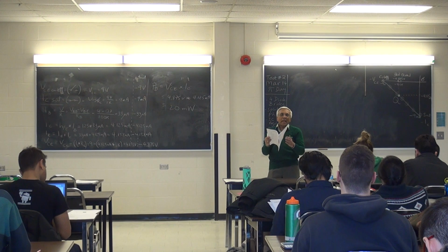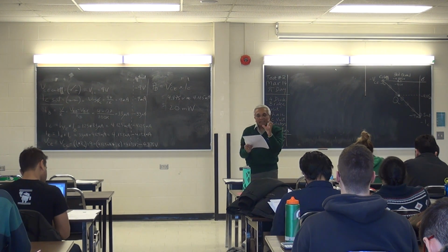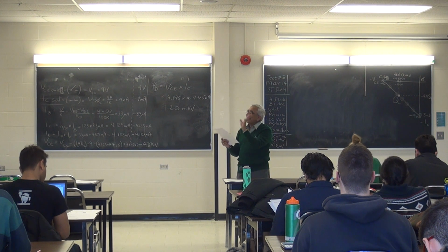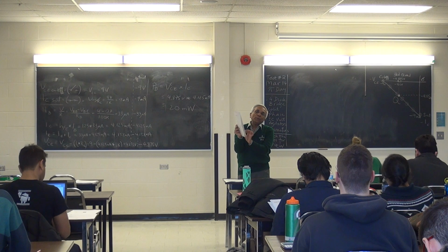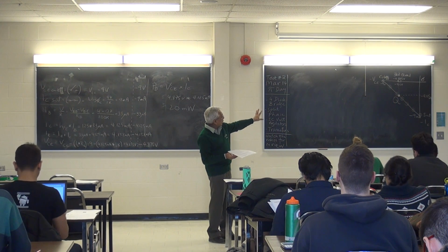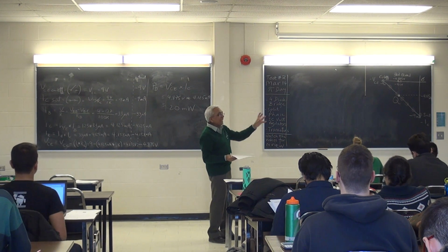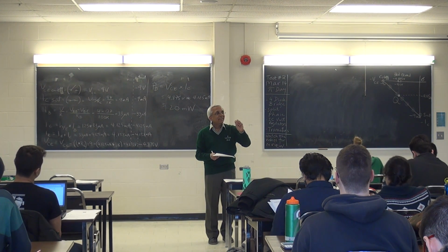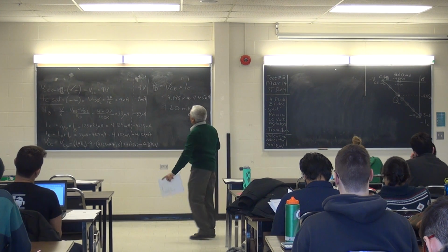And the whole point is to come up with different amplifier circuit designs. That's what the different biasing circuits are. So the base biasing is taking my regular circuit that I looked at in notes 10 and combining VBB and VCC into one. That's what DC base biasing is.